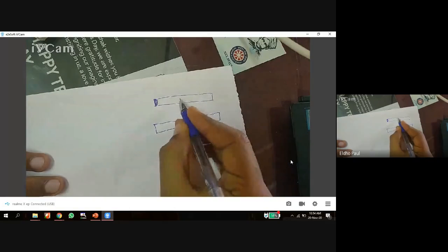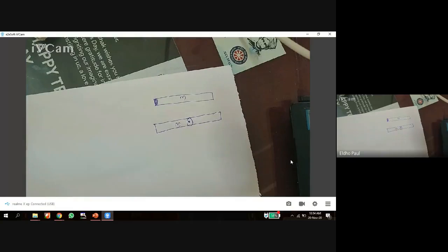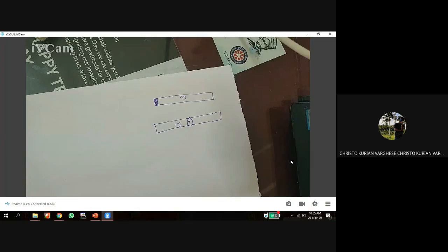you can rotate it easily. But when you rotate it holding at this end or the opposite end, it will be very difficult. You can check it if you want. So what is the reason for that? The mass is same here, the mass is same here also, but when I change the position of rotation I feel difficult to rotate the rod. What is the reason? The distribution of area around the centroid on either side is different as we move along the centroid.